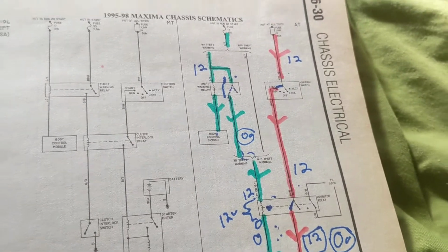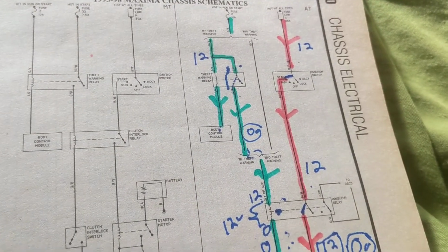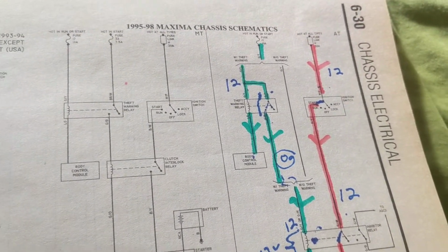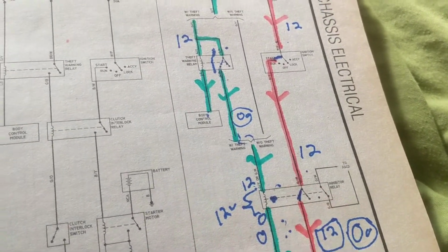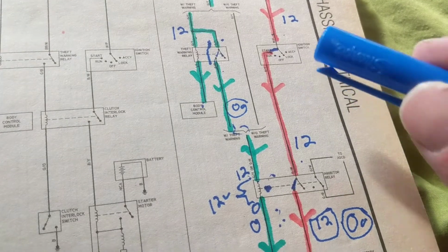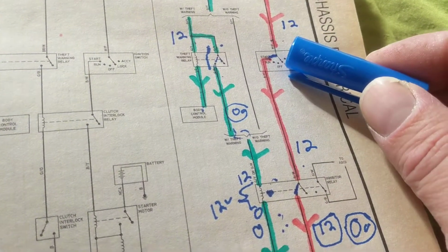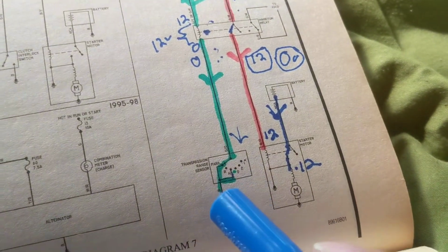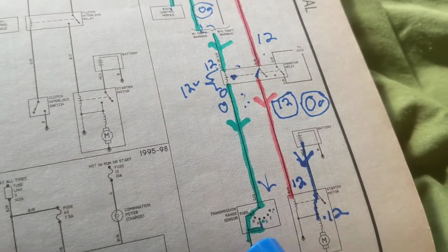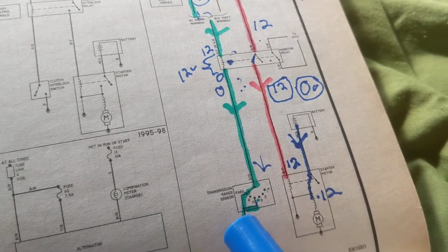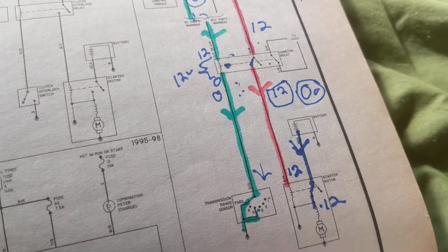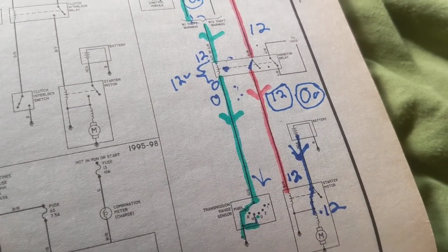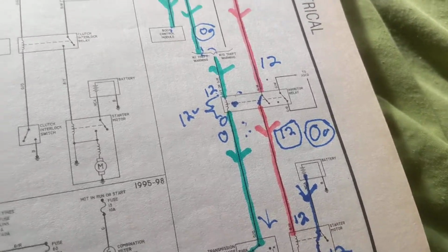Like I said, even though it's a Nissan Maxima, Toyota, Hondas, whatever, it doesn't make a difference. The theory is the same. There might be another computer involved, but relays are always involved, and you always have to be in the start position, and you always have to be in park or neutral. So if you have a problem, you might not be in park or neutral. You might have a problem with the park neutral switch. So instead of park, put it in neutral. See if it works.